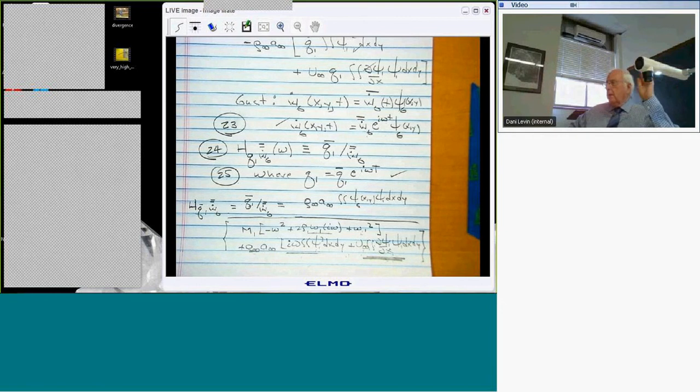It depends on where you are. At high Mach numbers, you probably would expect to get an answer compared to experiment or flight test within 10 or 20%. In the transonic regime, if you got that close, you would think you were very lucky. Very lucky. Okay, so now we need to do two-mode flutter.